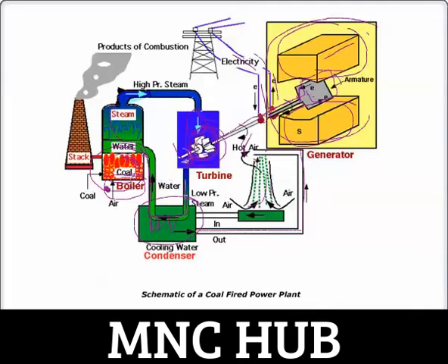Basically, about 30-40% of the energy that we put into this device is actually dumped out into the environment, into the atmosphere, through this condenser or cooling tower. That is the reason this turbine part is notoriously inefficient, and the boiler part is pretty good actually. It's about 90% efficient. This is about 40% efficient.